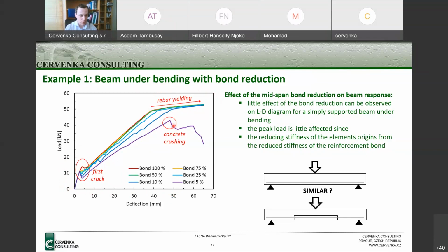we can see a different failure mode, which was some crushing of concrete between the cracks and in the compression area of the beam. From some easy engineering representation, basically what we did was simulating this kind of problem. Even if it can be seen that there is no bond in the center, what do I need to transfer the moment load? I need the compression area. I need the tensile, I need the reinforcement to transfer the tensile loads, and then I'm fine.